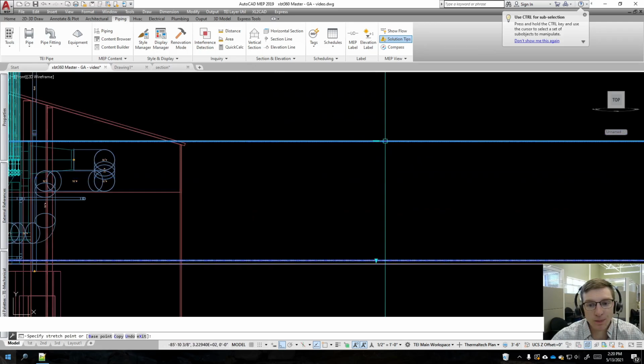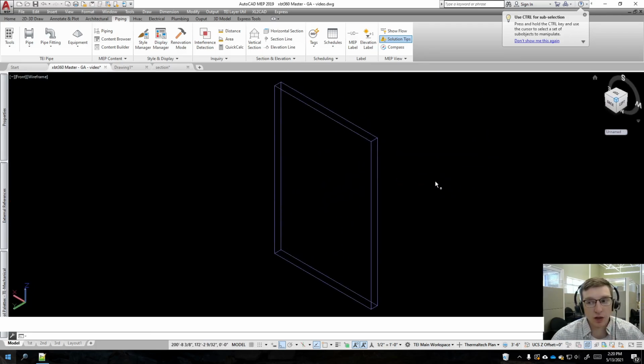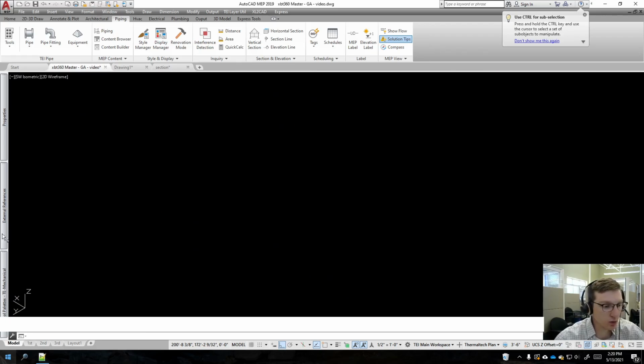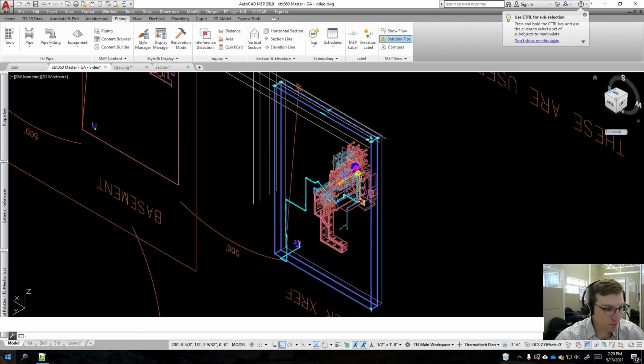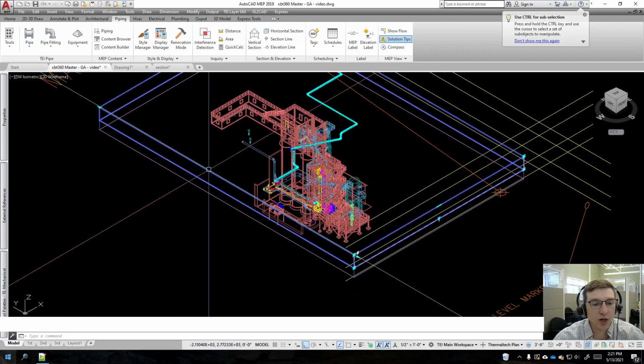Okay, do like that. Now this does not have the resulting section cut for this one yet. So in order to do that, we will just select that section box, right click, and you should find something in here that is insert section once it loads.